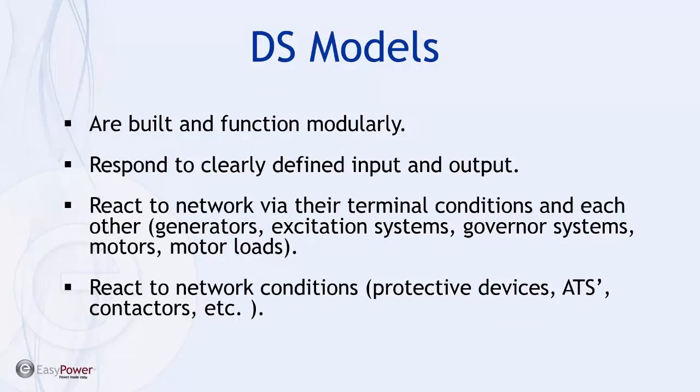So the models are built and function modularly, and they respond to clearly defined input and output parameters. Consequently, they react to the network via their terminal conditions and each other. For instance, generators, excitation systems, governors, motors, motor loads all connect to the system, and based upon their terminal conditions provide a change of state that then is connected back to the other models through the network.